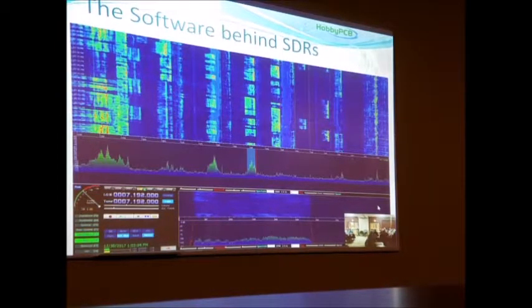We're looking at 40 meters here in the center. We're tuned to a lower sideband signal, and you can tell sort of from the waterfall display above it that it's a couple stations in varying signal strength. They were rag chewing as I was making this screenshot. And over to the right, that looks like a broadcast. It's certainly an AM signal. You see a strong carrier and sidebands on either side, so that's probably a broadcast. And at the extreme left here, that's a sort of a big pile of signals. Maybe that's a DX pileup or something going on.